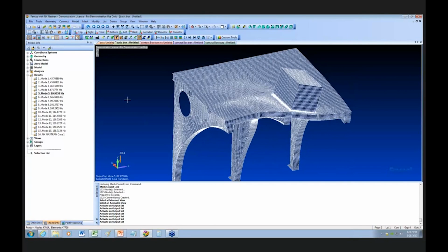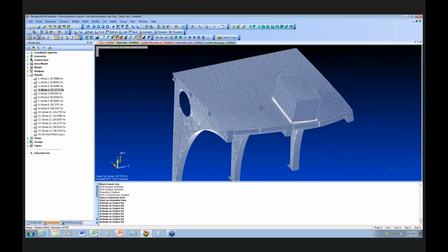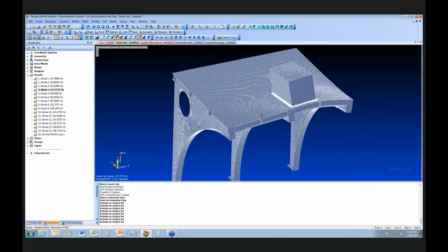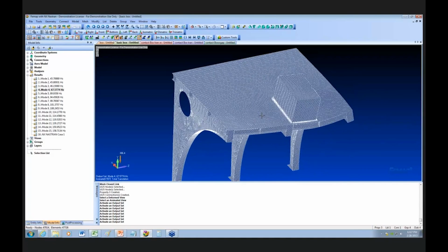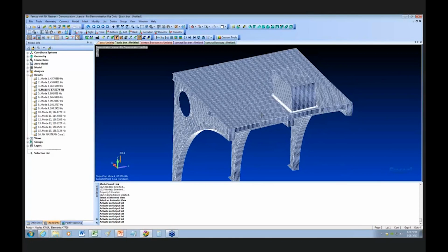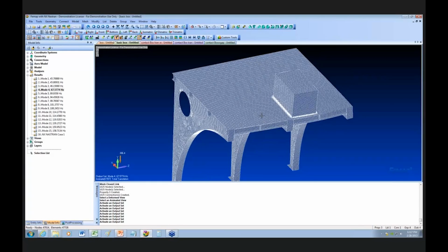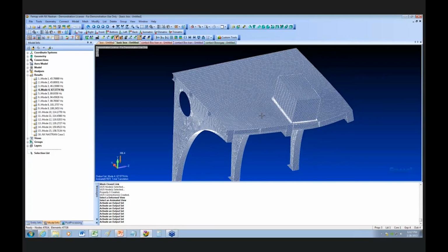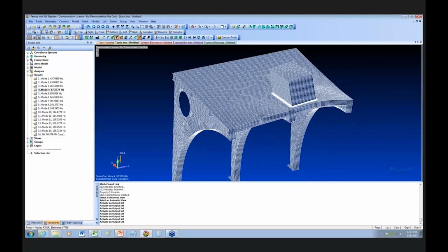Now, what I did is I put a damping constant on this. I said most of the energy when it strikes this platform will go into this mode here. I need damping because that's what happens in the real world, and it takes energy out of the structure and damps it out. I applied a damping coefficient to this frequency, and I had to do it that way because I'm running a direct. Now, it's interesting, as I ran this and looked at the response, I started looking at peak to peak.